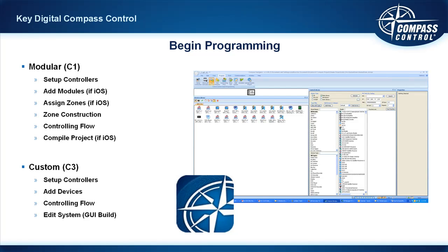Modular systems, again: a modular system has the events and actions already on the module and already on the button. So if I press the Blu-ray button, it should automatically have on it the macro that is needed so that the TV is on and it's going to switch to its proper input, and then the switcher or AV receiver is on and it selects its proper input so that the Blu-ray player is what you are viewing on the display, right? So what we do, we follow step by step.